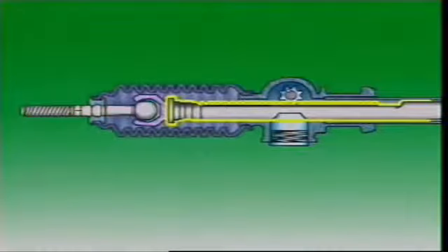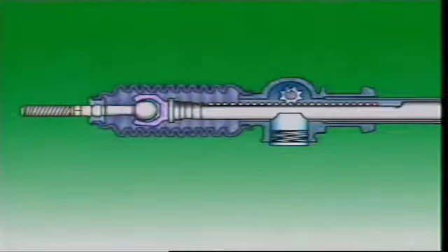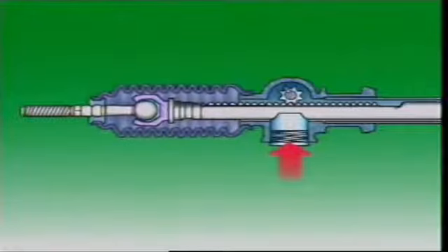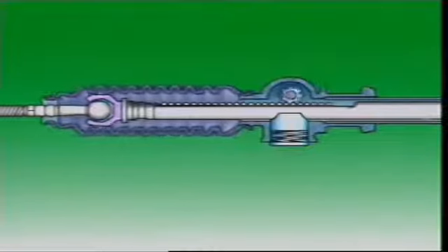The steering rack is supported at the pinion end by being sandwiched between the pinion and a spring-loaded rack guide yoke. This spring-loaded yoke ensures free play is eliminated between the gears, while still allowing for relative movement.